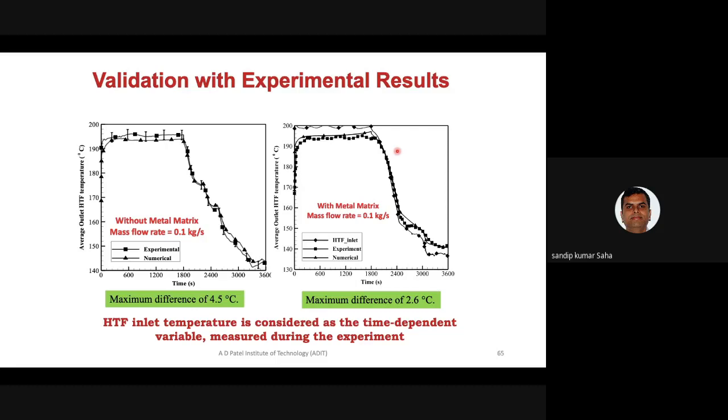Again, I told you why deviations are there: because I don't model the phase change behavior using the Navier-Stokes equation. If I am able to do it, it should be coming actually. But again, there will be restriction because of the Fluent side. If I am able to write my own code, then it is okay; I have to write one more Navier-Stokes equation, basically, for this case.